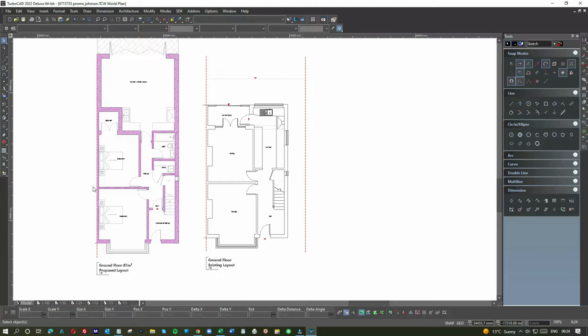Again, this is a structural wall all along here. It takes the weight of the wall above and the roof on top of that. There should be some supports sitting on top of this. So we look at this as a load-bearing structural wall. It could well be a structural partition, which means a timber wall filled up with bricks and block, or brick on edge inside. Fine. So again, a little bit of storage, and here now we created